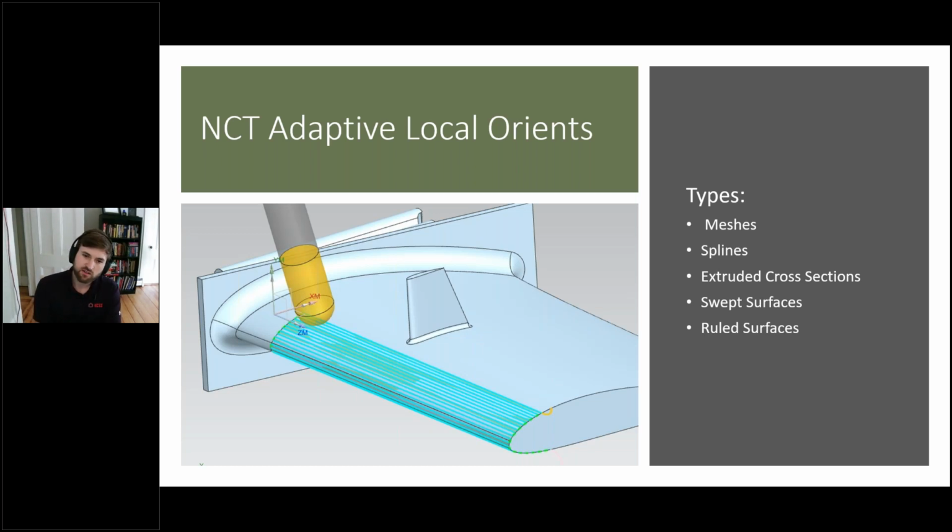But some applications, and one you see on your screen here is for the surface of an airfoil. So a lot of times these airfoils need rework, or they need some type of casting gate machined off. But we can probe around those areas and see what that part actually looks like and adjust to them.